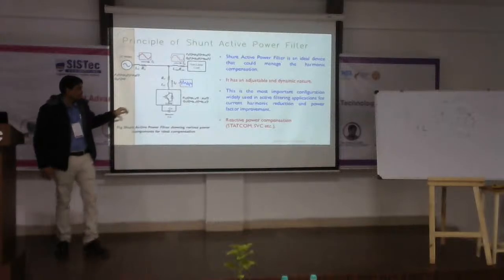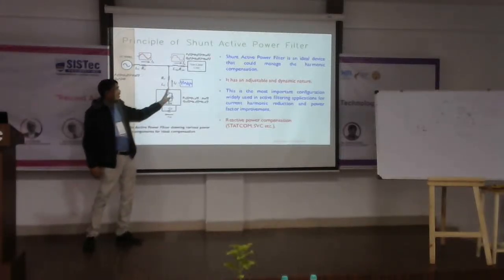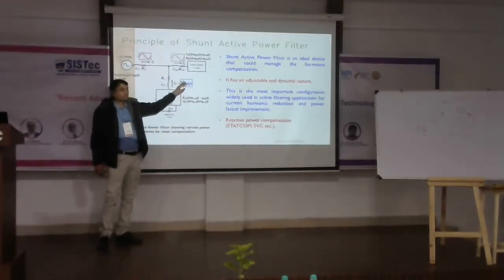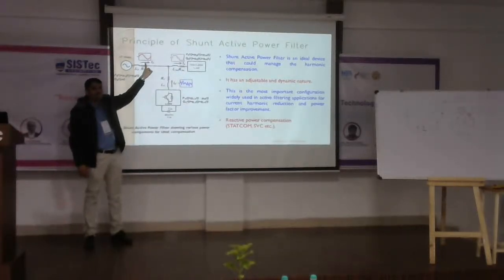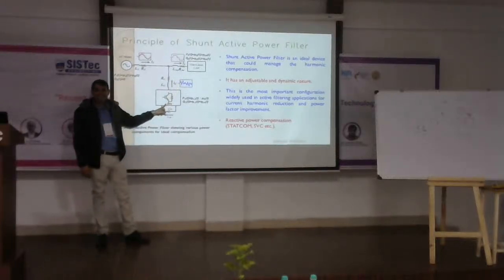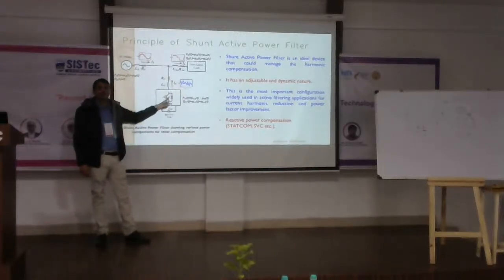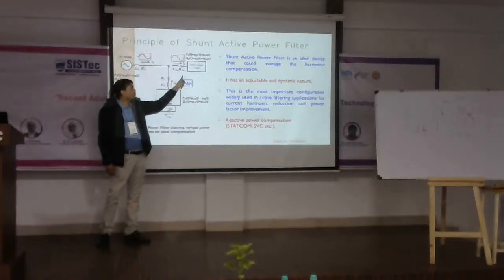Okay, so simple. What is the function of the subtractive filter? Whatever current is required, it will provide the current in just the opposite phase. So these two currents will add on and become sinusoidal. Whatever current is required will be generated by this subtractive filter. Getting my point? And how is the current decided to be developed? By taking a feedback. Which feedback?